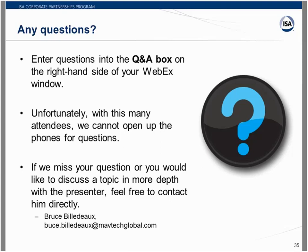Also, vendor design tools are good. Most of the vendors actually have network monitoring equipment already for just quality of service, and monitoring that traffic from a level is a great way of doing detection. A lot of your switches will actually have that kind of monitoring now. A nice low-cost industrial switch will have its own embedded tools, looking for data storms or repetitive broadcasts that are outside the norm. That software is built into the switches, and it will send out alarms to appropriate personnel.